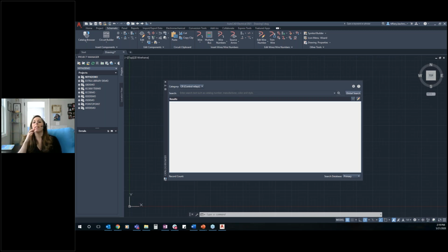However, one of the top things I recommend for any implementation of Electrical: you are going to spend more time trying to repoint other people's machines than doing this from the onset of installation. Many people don't even know that you can do this. When you go to install, you should click where it says AutoCAD Electrical 2021, and there's a little configure software button.